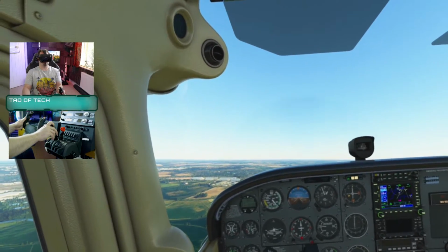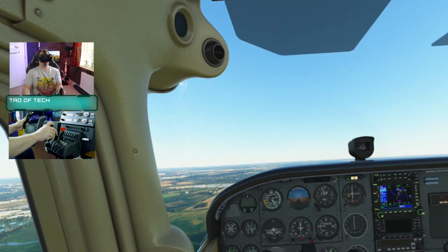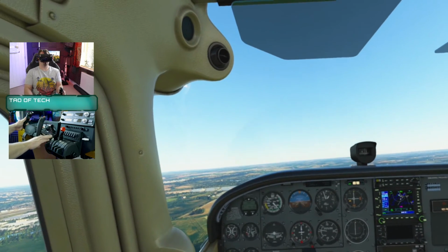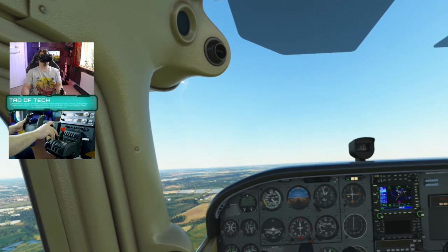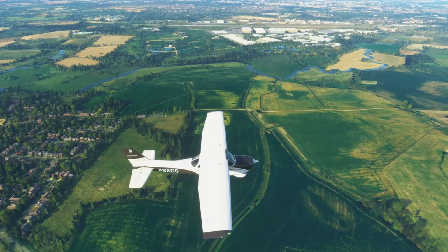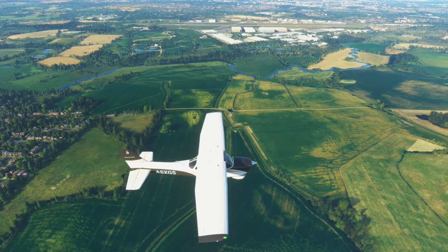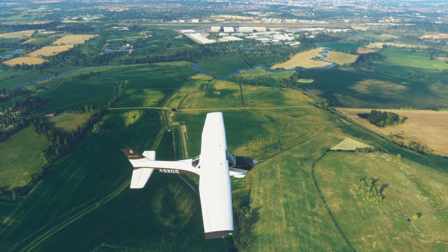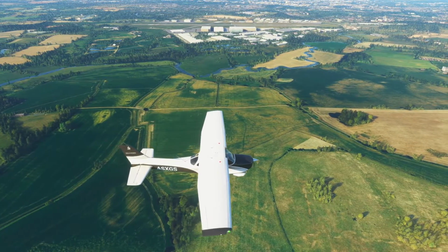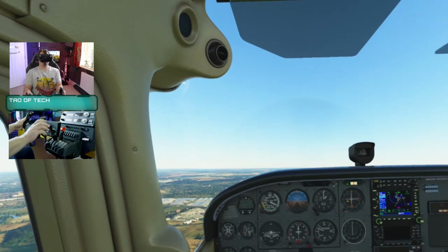So reducing to 1900 RPM and then trimming for straight and level flight. The other great thing is that when you're not looking directly ahead, you still get a sense of whether the aircraft is pitching up or down, or whether it's rolling to the left or right. So despite looking in a different direction, you can continue to apply control input to correct for these.